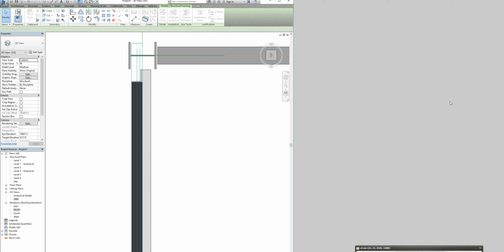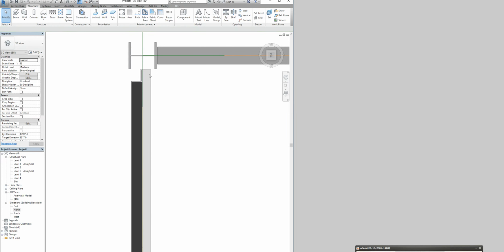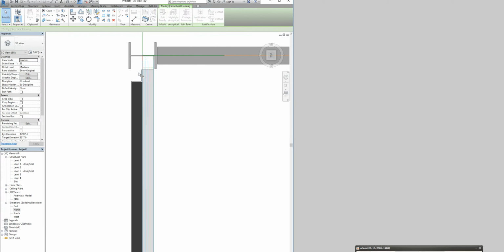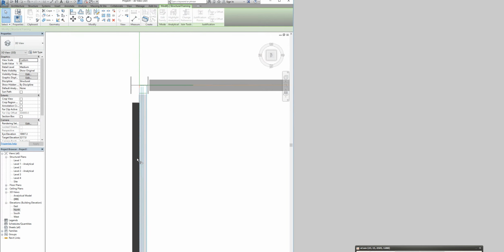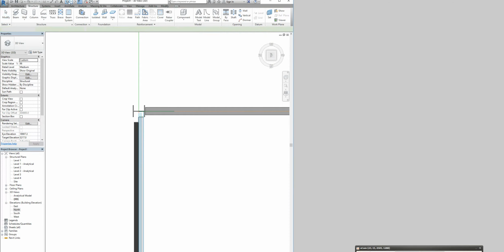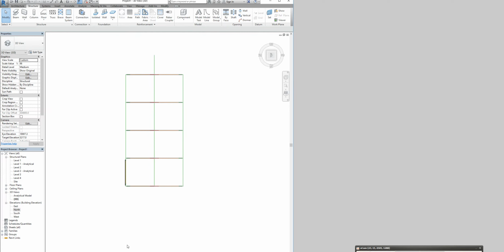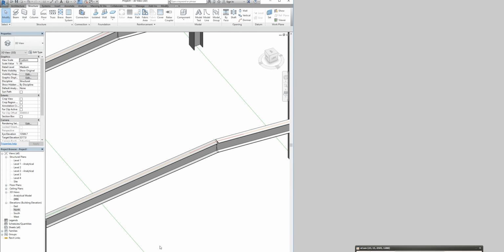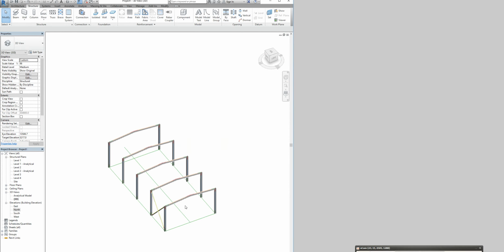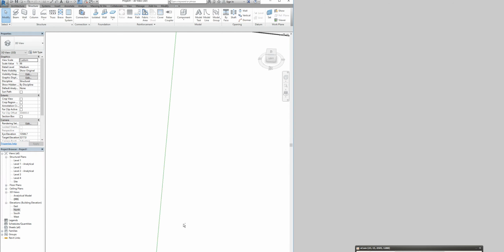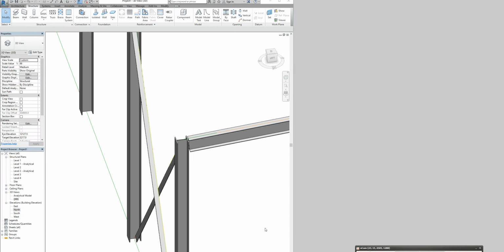And repeat the process with the second brace. So basically I select the brace, go to justification points and select the outer corner. So now I got the brace components aligned. If we see here in 3D, see how they're not intersecting. Sorry, the components are not intersecting anymore.